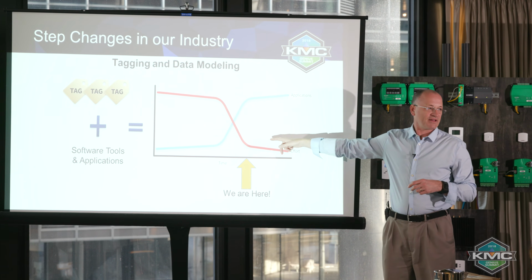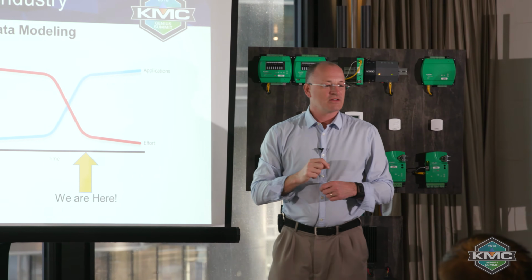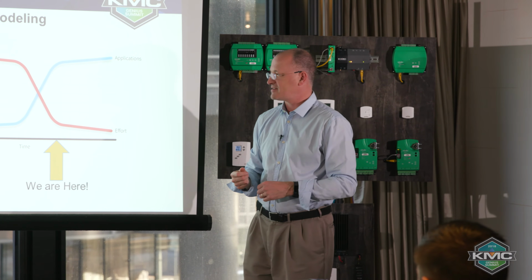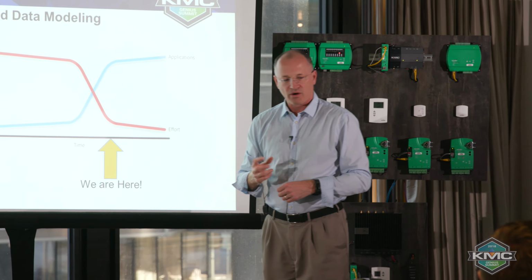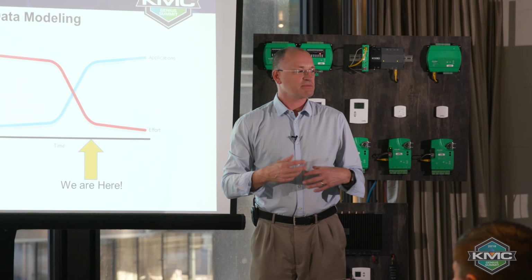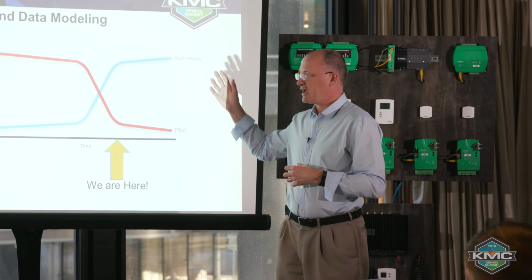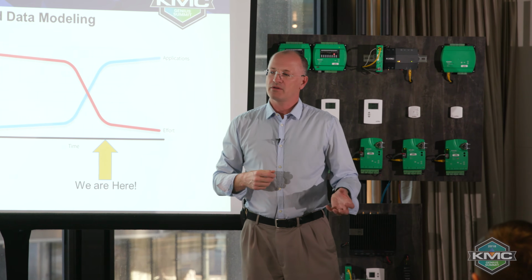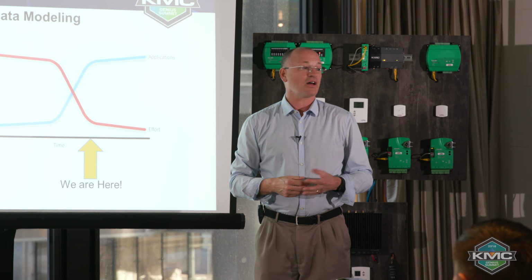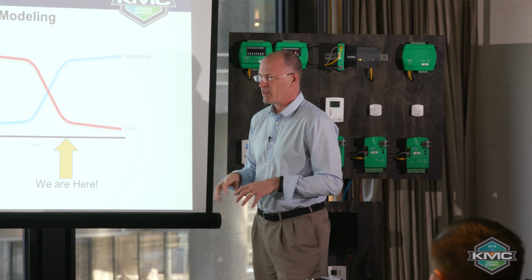And the amount of effort it takes to get them connected and get them talking to those applications is going to go down significantly. And the reason for that is because we're going to add one little piece of information to our real world, and that's called a tag, or metadata in the most generic sense. And tags are basically a way for a computer to know something about a piece of information. So that's my working definition for today. A tag is a way for a computer, an application, a tool, to know something about a piece of information in the real world. And for the context of HVAC, let's call it a point: space temperature, discharge temperature, fan command, that kind of thing. And then we'll build up from there.